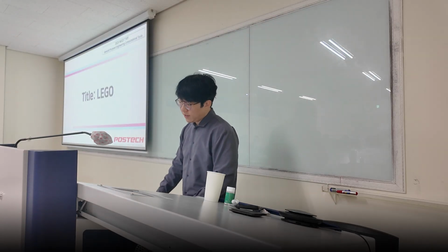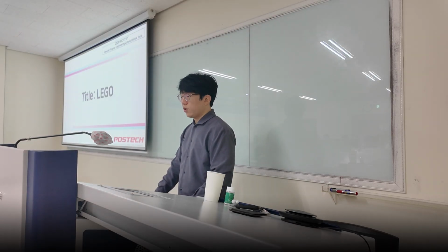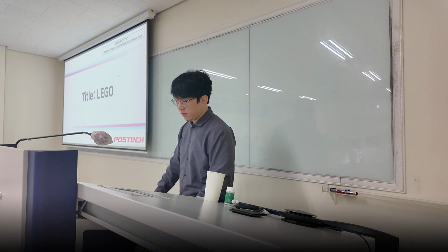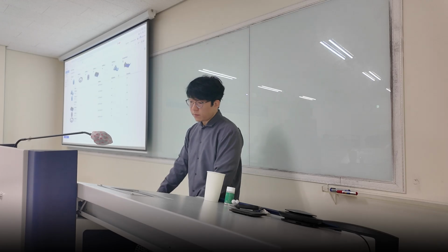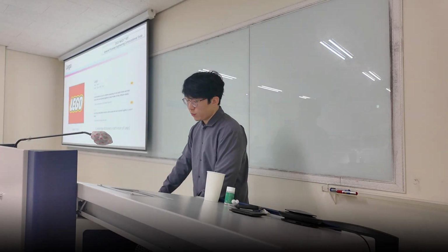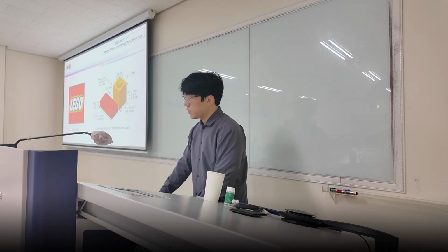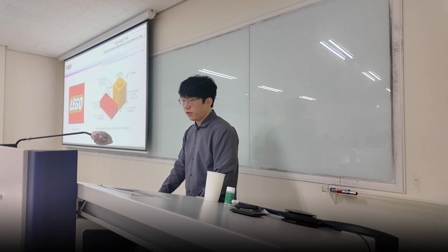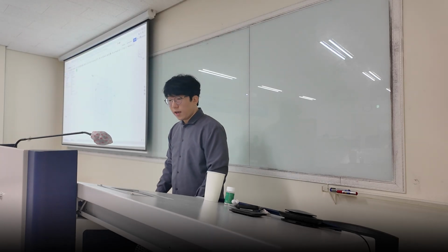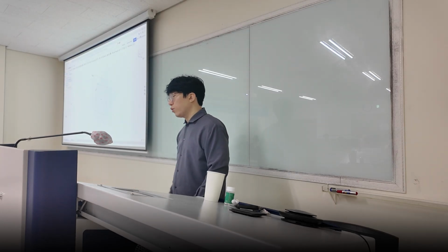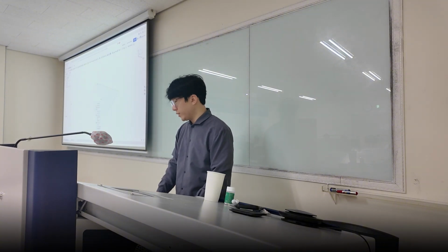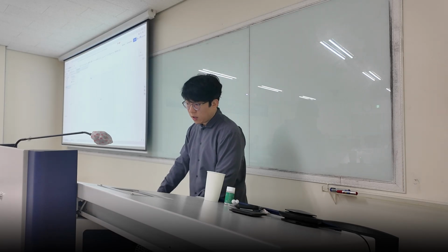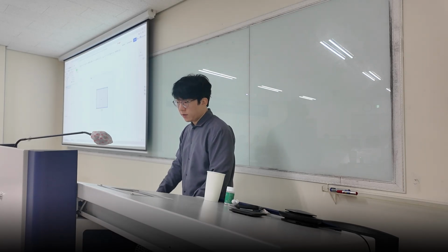And the second one is Lego. You can do the Lego one first before the pool boiling tutorial. So the Lego tutorial comes with a Lego block, of course. You can see these are the design specifications of the Lego block. And of course, we're going to start with choosing the right workspace units. And then we choose the top plane, of course. And then we draw a corner rectangle.